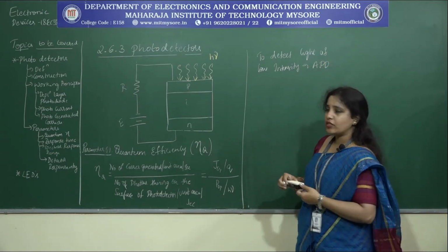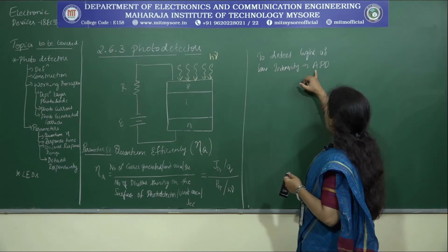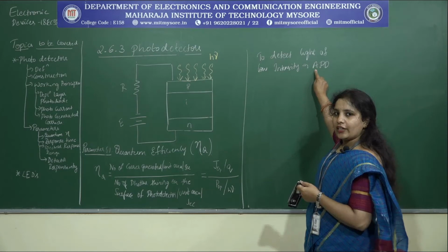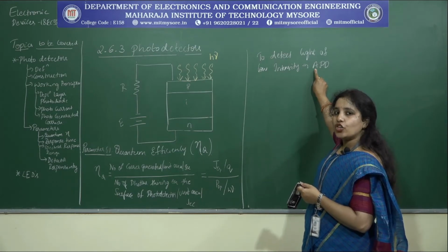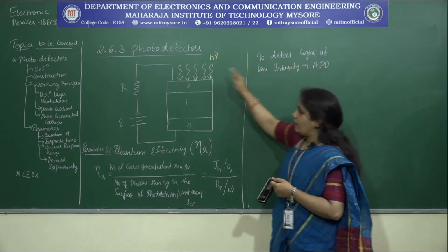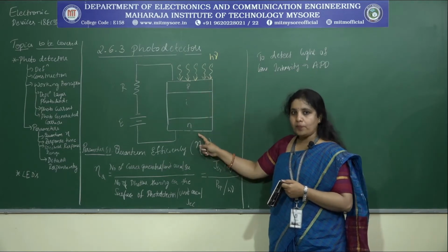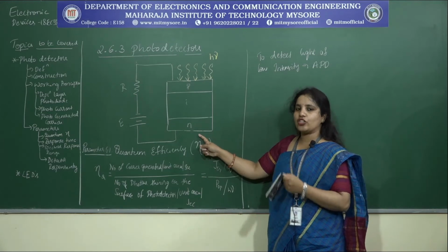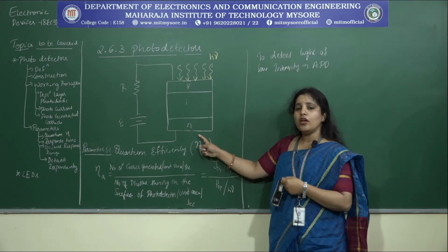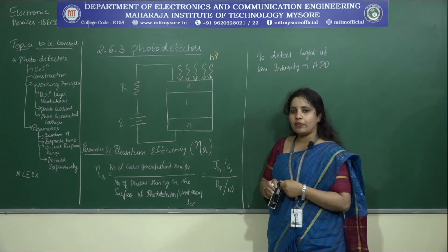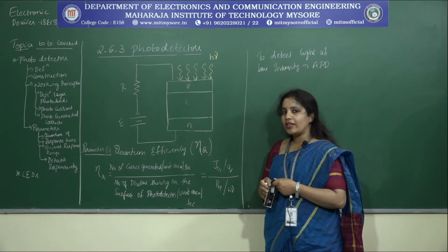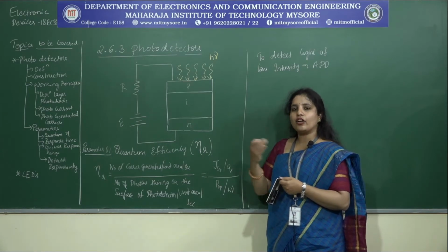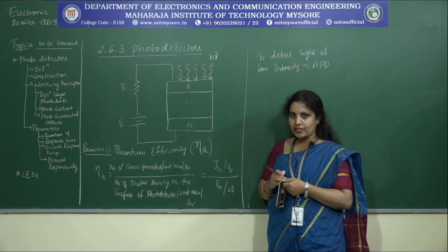These are referred to as avalanche photodiodes. Now, as the name itself indicates, the phenomenon is avalanche breakdown. That means I will have a pin photodiode that operates near the avalanche breakdown region. Now, we know that when avalanche breakdown happens, the carriers get increased. Carrier multiplication takes place. As a result, an enormous amount of current flows across the device.